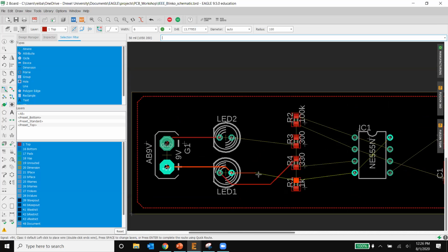So what you want to do is, if you press the space bar, you're going to have a via. And the via is basically a copper connection between two layers. And that copper connection between two layers is so useful because it's going to take you to another layer where these two lines do not meet up anymore with each other. So now if I press left click, you're going to see here that the layer is blue right now. That means that it's the bottom layer. So I can go freely here and not worry too much about it.